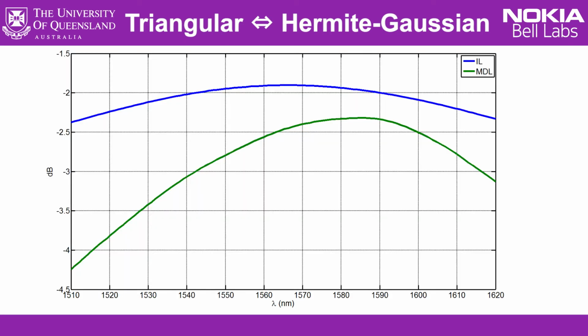In terms of the performance, it's a bit worse insertion loss and mode dependent loss, and not quite as wide bandwidth compared to the quasi-spot example from before. This is a quick little demo simulation. You could optimize that a bit more, center the response a bit better for the mode-dependent loss. But ultimately, the point here is that we've used less than a third of the number of planes. 45 modes in 7 planes, and got a sort of comparable level of performance.